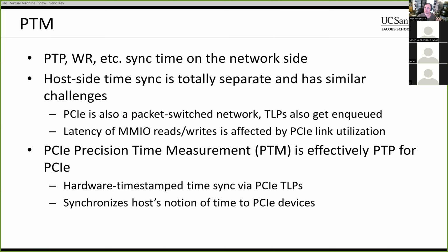And now, right on the card, you'll have both the host notion of time and the local clock that you've synchronized via PTP or White Rabbit or whatever, and then you can compare those and figure out who's running faster or slower and make the appropriate changes on the host end. So this basically removes the variable latency of the MMIO operations from the picture.